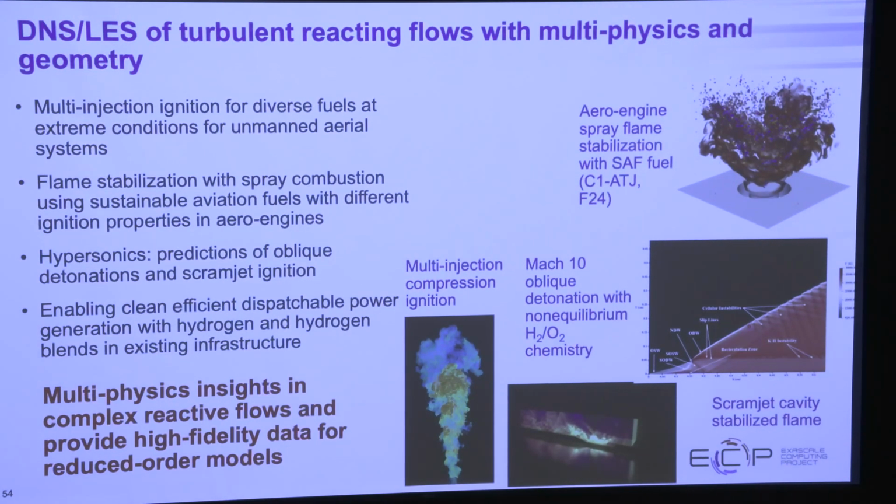We've also dabbled in, not dabbled, but we're working on hypersonics, and so we're looking at predictions of planar and oblique detonations and also flame holding in a scramjet ignition type problem with this capability. And we've been using this code also to look at dispatchable power generation with hydrogen and hydrogen blends with ammonia in rich quench lean kind of combustor technologies.